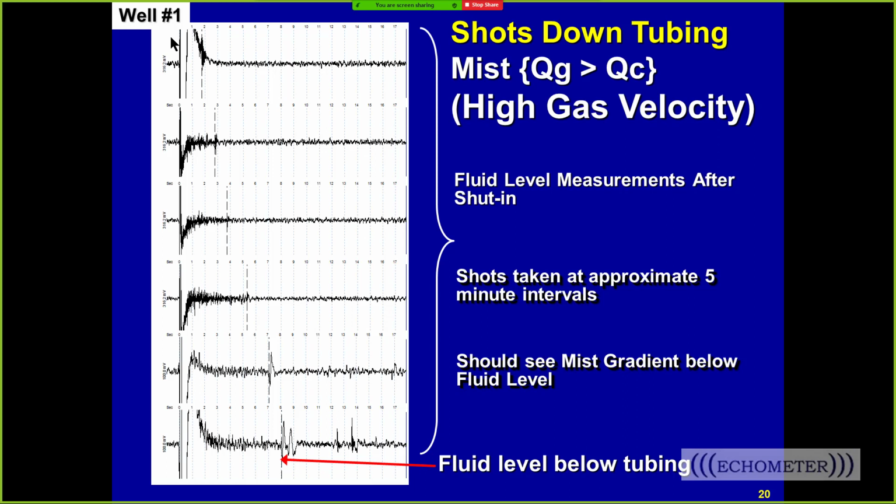Usually the casing will add water, and the tubing usually will leak out water. So if you have a hole in the tubing with a packer, usually the liquid level is going to be down near the hole in the tubing, and the water will have leaked out. But if it's a casing leak and it's coming in from the casing, usually, not always, the casing will add water and maintain a high fluid level. So it's either a packer leak or a hole in the tubing, probably.